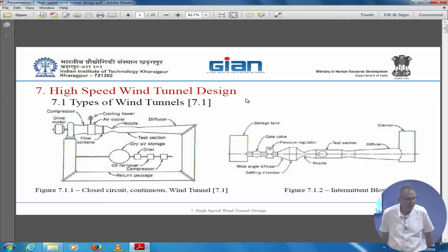When the air is closing, because the Mach number is decreased, the shockwave is coming back through the test section. Once it goes through the test section, it goes through the model, and you cannot guarantee which way it will go. Once it is inclined, you get all this pressure difference across the shockwave, and you get it as a force.